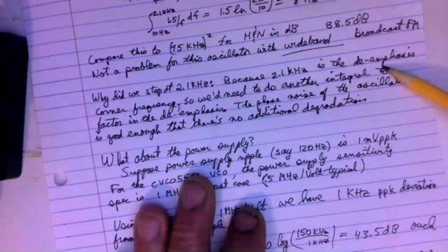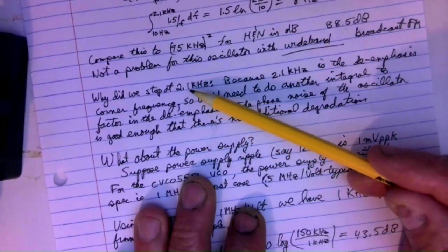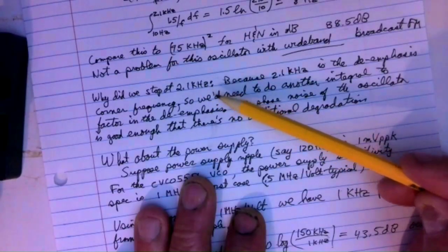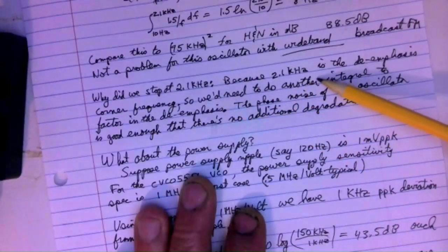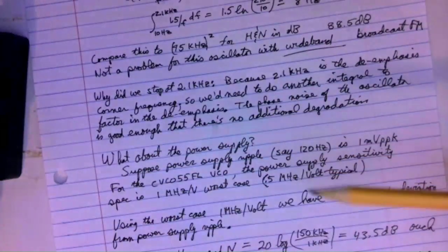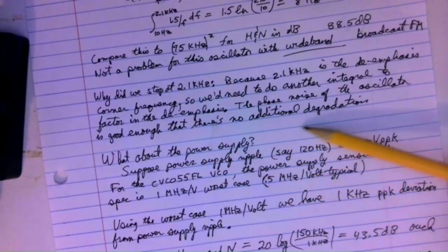If you really wanted to go farther, you'd have to go from 2.1 up to 10, with that de-emphasis filter kicked in, and then you change from the 1/f region to the thermal region where your oscillator rolls off less quickly, so you really need to start a new integral there too.